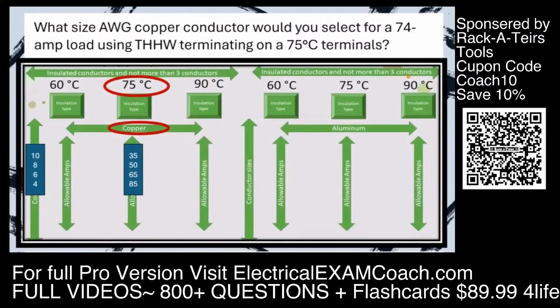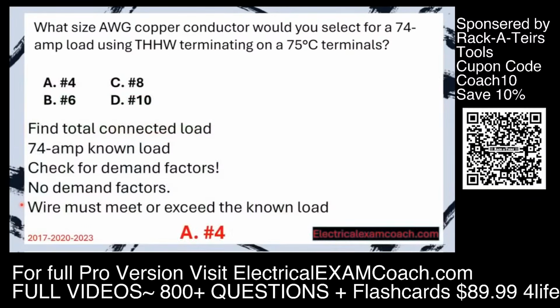We head to our primary ampacity table. We make sure that we're on the right side of the table. In this case, it's copper. And we have 75°C terminals. So now we take off and find a wire that will cover the known load. We find one that will cover 74 amps. We use a straight edge to come over and tee off at number 4. And we're going to select A.